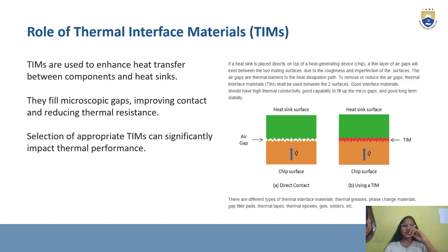Role of thermal interface materials, TIMs. TIMs, also known as thermal interface materials, are used to enhance the heat transfer between components and heat sinks. They fill microscopic gaps, improving contact and reducing thermal resistance. Selection of appropriate TIMs can significantly impact thermal performance.